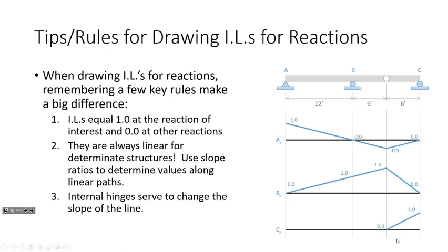So I move that through a unit displacement. You can see the shape. Notice that if from here to here is 1, then from here to here is higher than 1. See how it goes up? How do you know which direction to move it? You move it up. Always move it up. Well, for reactions, you move it up because a positive reaction goes up, yes. And that's a very loaded question for internal shears and moments. We're going to talk about that next time.